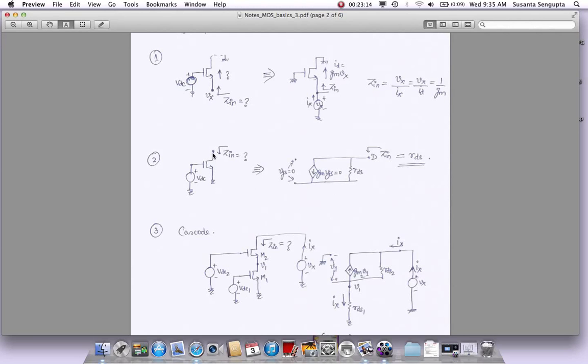As this drain moves around up and down, some small signal swing or large signal swing, whatever it is, it will have an equivalent impact on the value of this current, because we know that in saturation the current is not flat, as we have seen in the ID-VDS curves. Since it is not flat, it's given by a finite RDS, even though this value is large, and it will cause a change. So that's why we put this device in series with this, as we did here, because this guy now acts more like a shock absorber. There is a lot of swing that could happen here caused by other circuitry which are here.